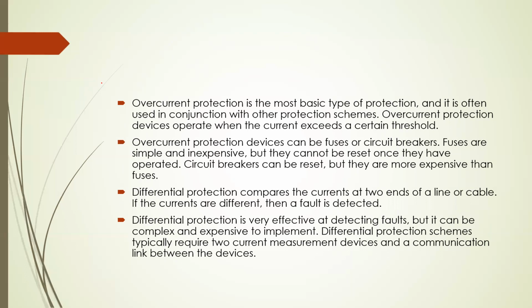A fuse is a device which blows out and isolates the two lines or two grids from each other, two systems from each other, and another fuse should be placed in the place of this fuse in order to again continue the line or close the line. But in the case of circuit breakers, the circuit breaker will trip or switch off and isolate the two systems. After finding the faults and solving the faults, we can switch on the circuit breaker to again continue the connection between the two systems.